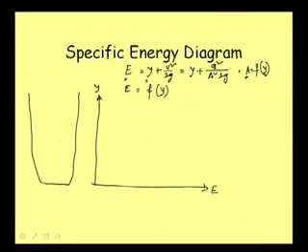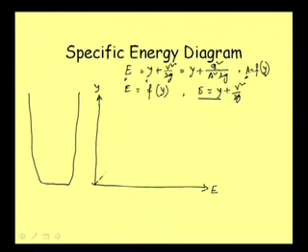This will indicate the different depths. From the expression E is equal to y plus v square by twice g, the line for E is equal to y will definitely be a line drawn at 45 degrees to this axis. So if I draw a line at 45 degrees, this line is nothing but E is equal to y.